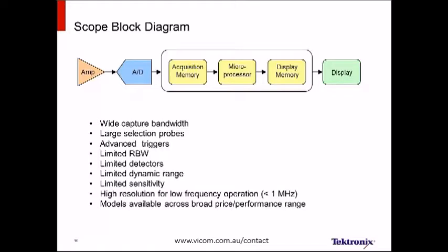One area where I really like to use oscilloscopes is for low frequency application with the high resolution sampling mode that's in the oscilloscope itself. We can get extremely high dynamic range, extremely high frequency accuracy when we're looking at very, very low frequencies. And I'm talking here about AC mains frequencies.